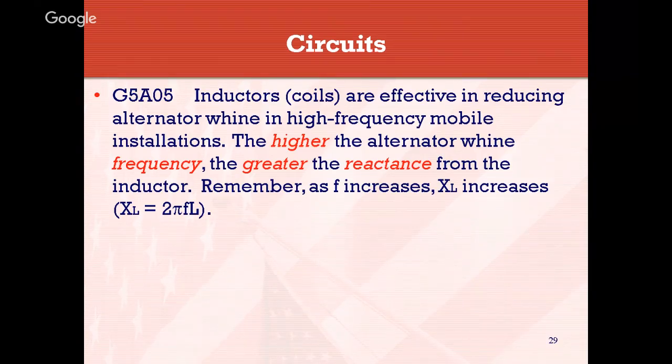Inductors are coils and they are effective in reducing alternator whine in high frequency mobile installations. The higher the alternator whine frequency, the greater the reactance from the inductor. So remember, as frequency increases, inductive reactance also increases. Again, there's your formula.